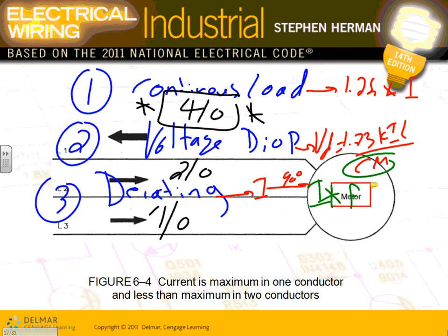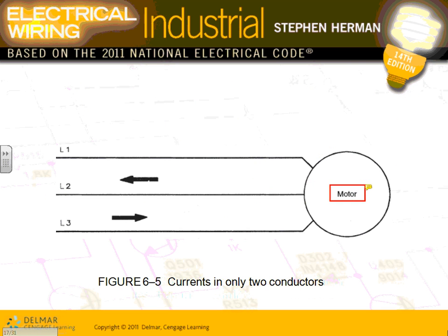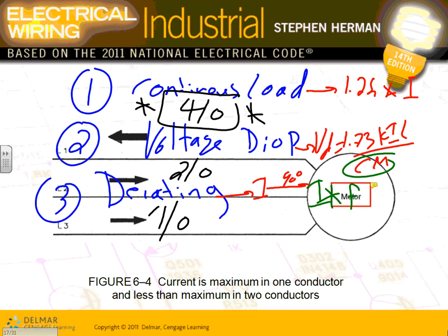Chris was running some calculation sizing based on voltage drop, and they give you a ridiculously small conductor. If you run a voltage drop calculation on a feeder, 10 feet, if you try, guys, do a calculation on a 10-foot feeder, it will give you a ridiculously small conductor. So should I stick with that one? No. You do the three calculations, and you choose the one that gives you the largest. Can I get you guys to understand that one? That's the single most important thing. So this isn't just for feeders. Branch circuits, feeders, service conductors, you name it.